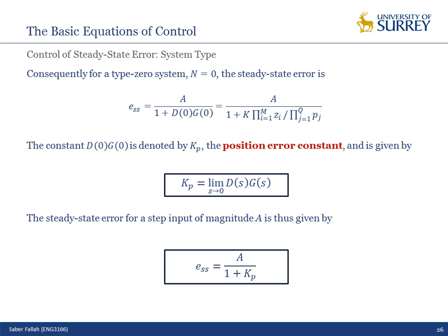Or in terms of a PID controller, for example, I have designed a proportional controller, but I have a steady state error. I add the integrator controller in order to increase the type of the system, in order to increase Kp, and make the steady state error 0. Look, if I have no integrator for the step input, for example, Kp will be 0. So steady state error will be a. If I add just one integrator, I will have Kp not 0, but not infinite.